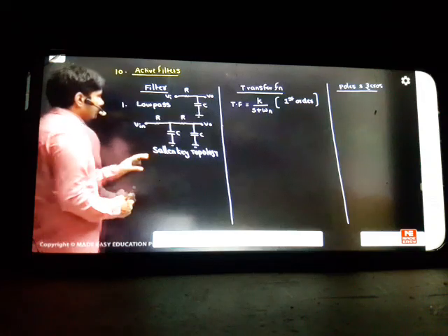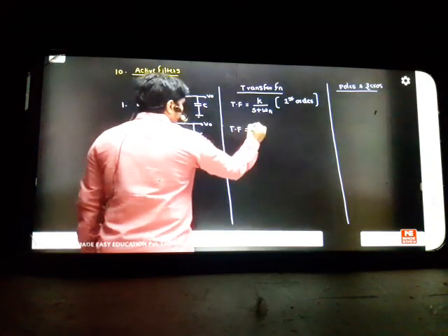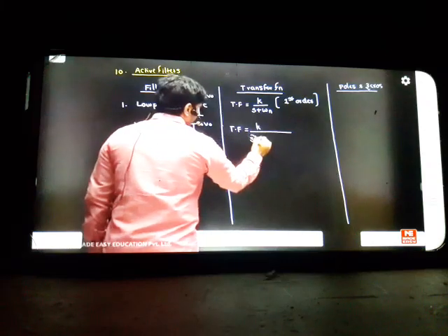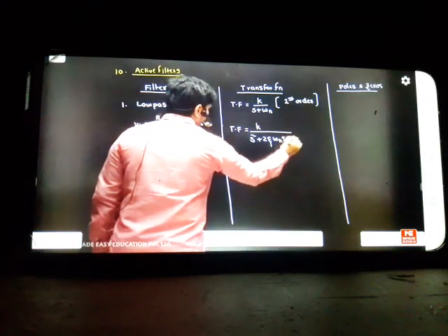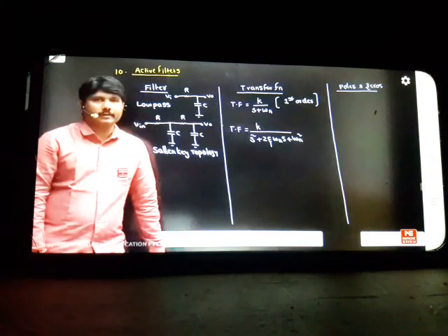So this is called a Sallen-Key topology device. We are designing this technique. The transfer function you must get after designing the Sallen-Key filter should come in the shape K by S square plus 2 eta omega n s plus omega n square. You have to recollect this transfer function, whatever you derive, it should come in this shape; we call this a second order transfer function.